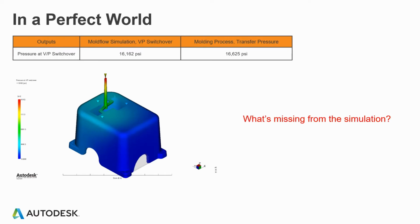And while you're thinking on that, the one thing I might point out is, what are we missing from the simulation? And the one thing that's not always done, can't always be done unless you have that kind of information, is adding the machine nozzle in. We're only predicting what we've modeled, and what we haven't modeled in this case is the machine nozzle. So in this case, the Moldflow results do not match real world. And in fact, we're probably over predicting pressure.